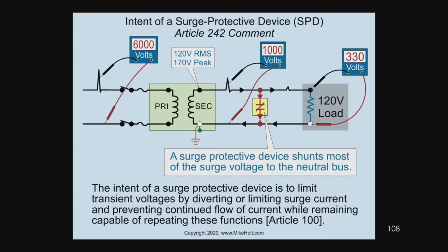So the key for the manufacturers is to design in a way to manage the heat when the MOV does enter into a thermal runaway situation. What causes a thermal runaway? Manufacturing anomalies can cause a thermal runaway. Repetitive overvoltage can cause a thermal runaway, such as a lightning strike or other transients. They can't operate indefinitely.